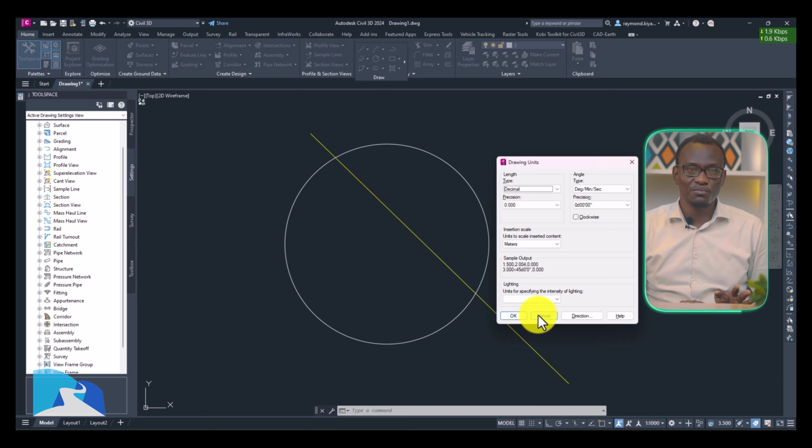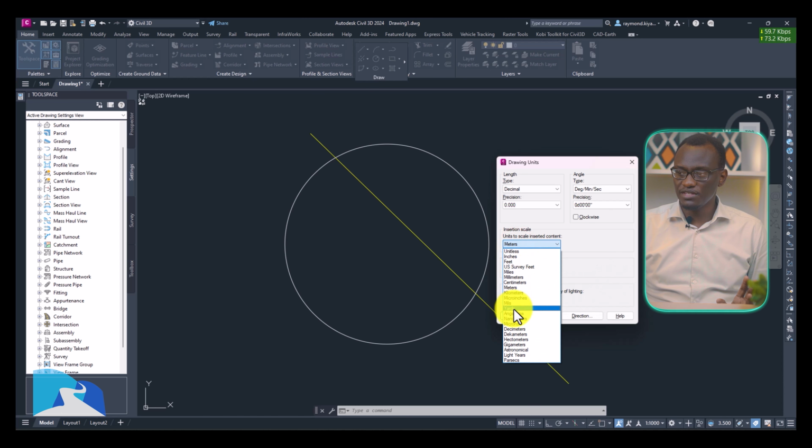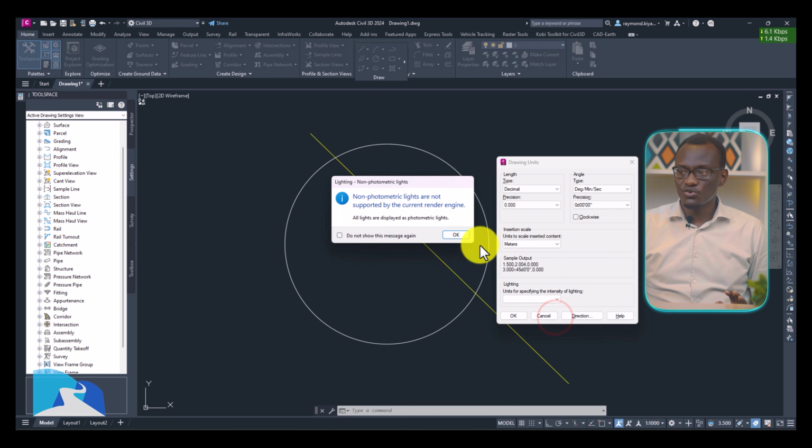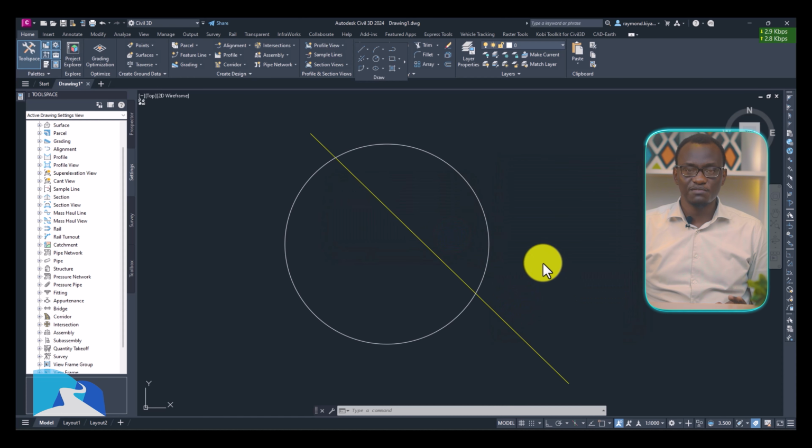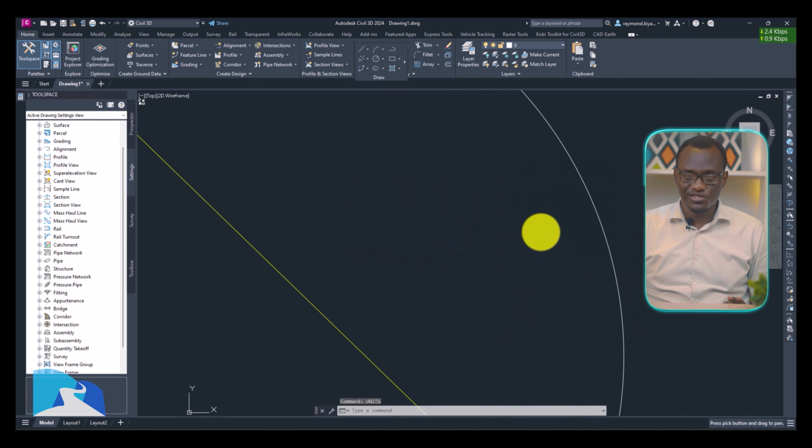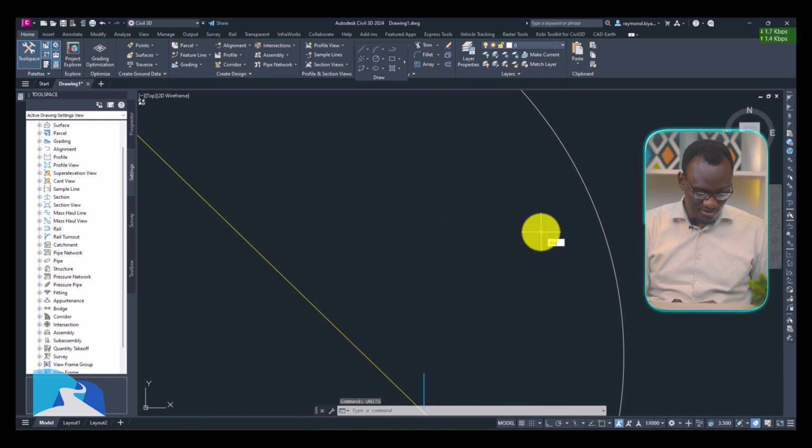They did know, but they drew it in imperial. Or the surveyor somehow forgot to do something. So what's important is most cases you find someone didn't put units, but maybe that drawing now should be in meters, but maybe it's in feet. And this is going to affect your coordinate system. So one of the most important commands, it's not important, but it's there, is DWG Units.